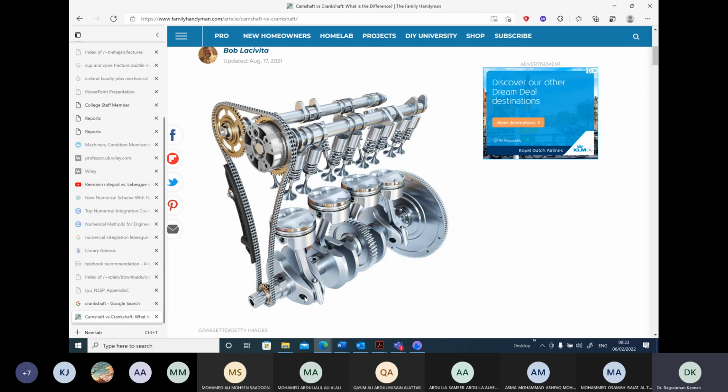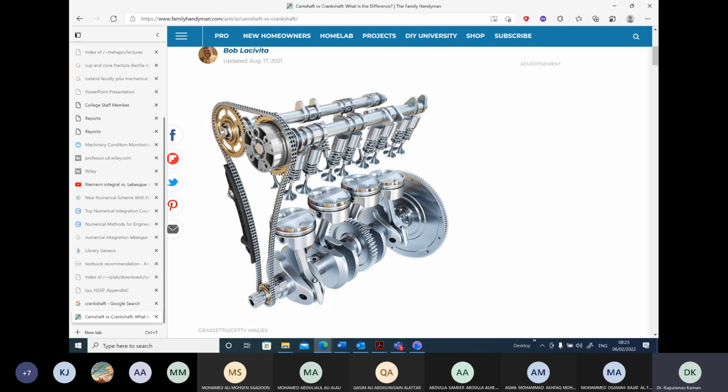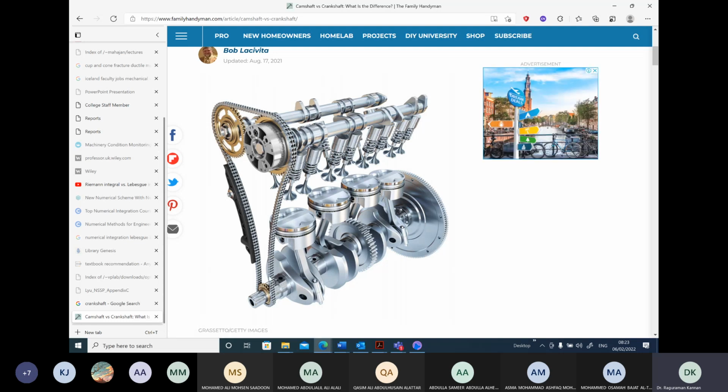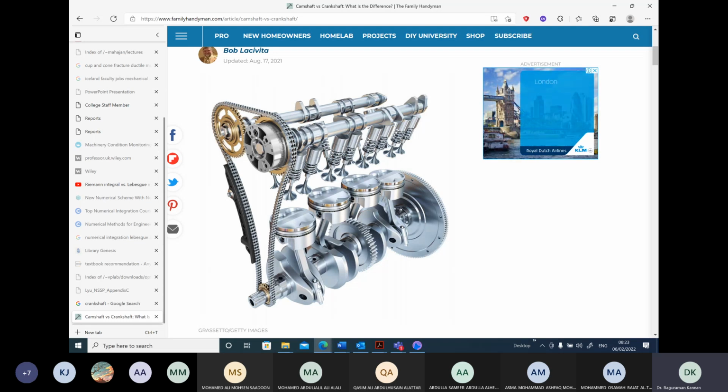Depending upon the angle of rotation of this crankshaft, the forces acting on this connecting rod will be different. Force may be higher at certain positions, lower at another position. For example, in this horizontal position, forces may be different. It could be that these are tensile loads acting on the connecting rod or compressive loads.